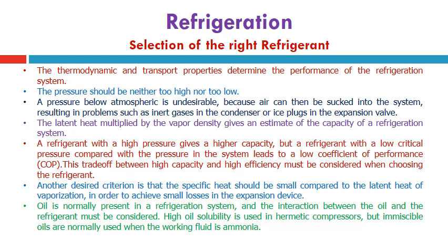Oil is normally present in a refrigeration system, and the interaction between the oil and the refrigerant must be considered. High oil solubility is used in hermetic compressors, but immiscible oils are normally used when the working fluid is ammonia.